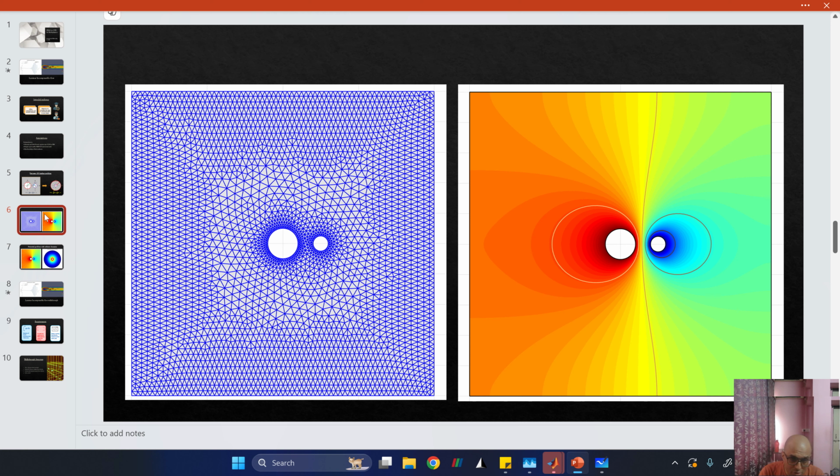We built meshes in Gmsh, and we also looked at the mesh quality, how to decide the mesh quality, and how to really do the meshing and read the mesh and develop a solver from scratch in MATLAB, Julia or Python. And these very simple diffusion problems were really a good test case for understanding all of those basics. And of course we also put in different kinds of boundary conditions like Robin conditions, and towards the end we looked at a very simple workflow in FEniCS for solving these diffusion problems.